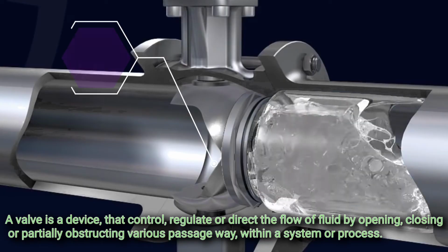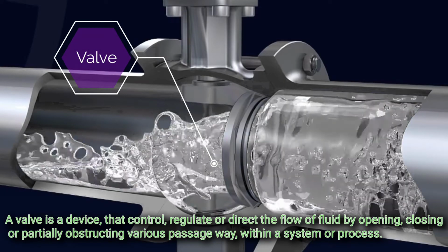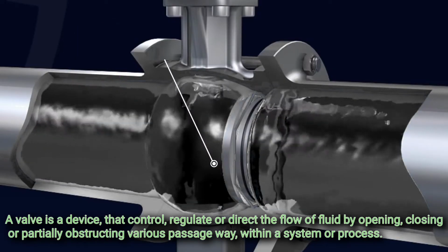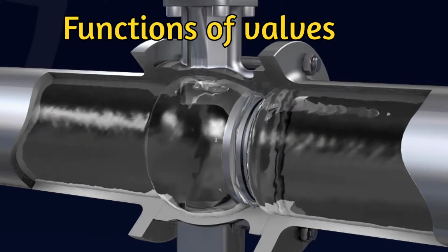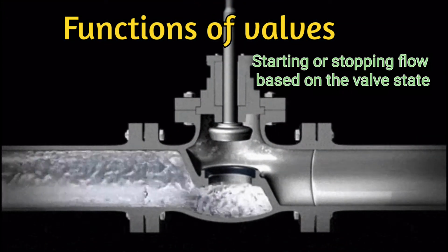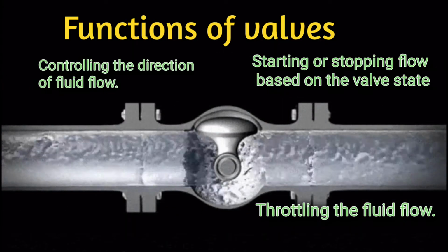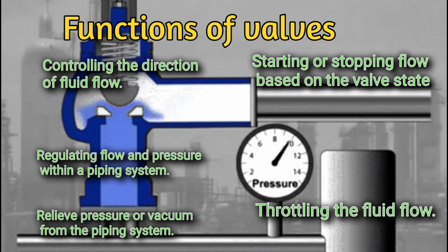A valve is a device that controls, regulates, or directs the flow of fluid by opening, closing, or partially obstructing various passageways within a system or process. The valve serves various functions within the piping system, such as starting or stopping flow based on the valve state, throttling the fluid flow, controlling the direction of fluid flow, regulating flow and pressure within a piping system, and relieving pressure or vacuum from the piping system.